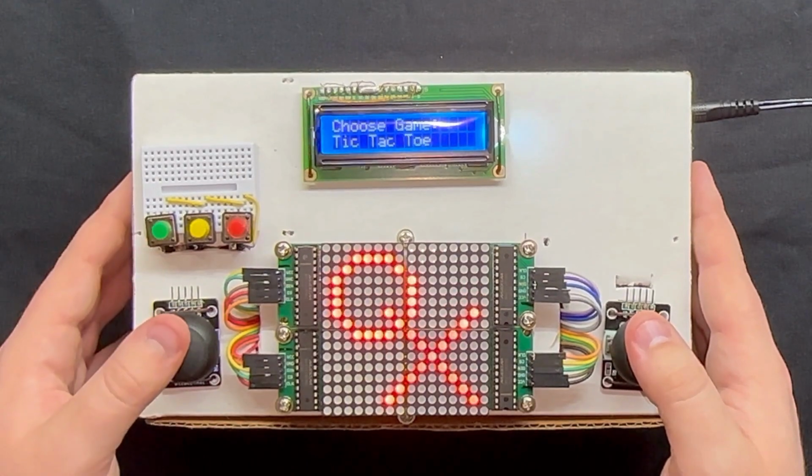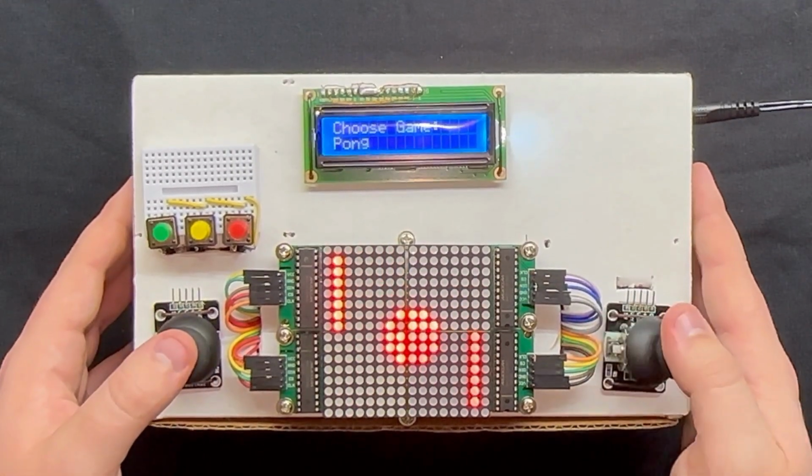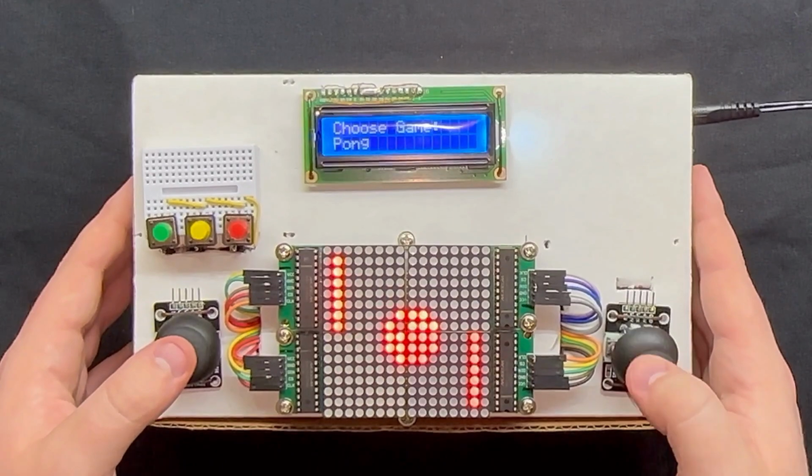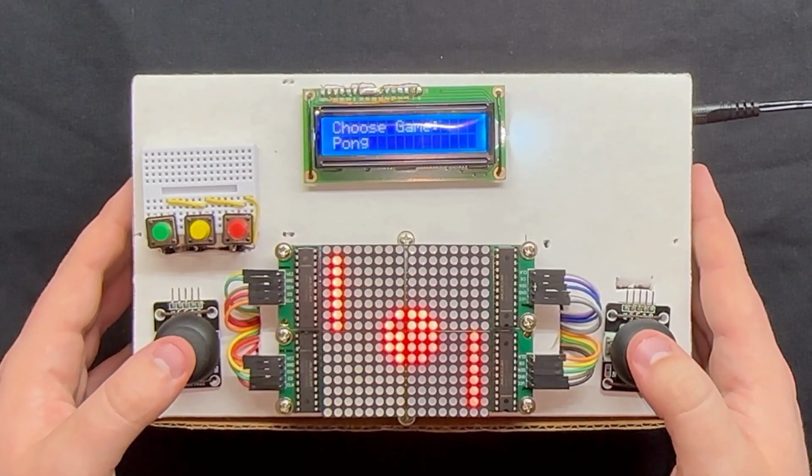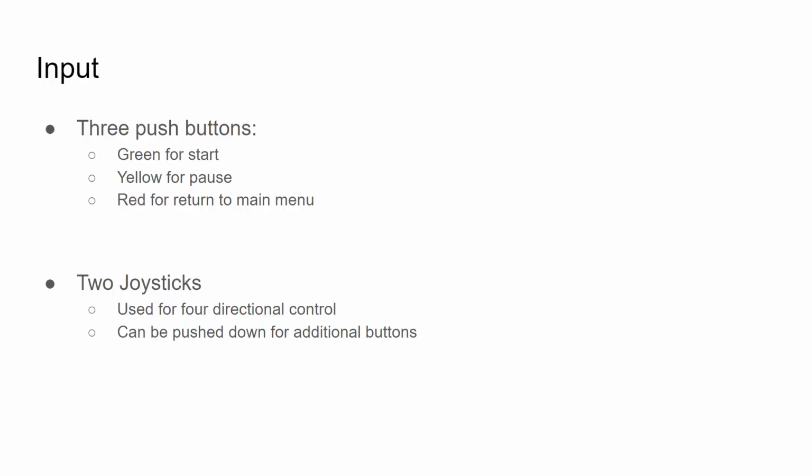The joysticks give out 2 analog signals, one for horizontal position and one for vertical position. We then use the ADC to tell us exactly the coordinate position of the joysticks. The joysticks also have the ability to be pushed down like buttons, allowing for further user control.